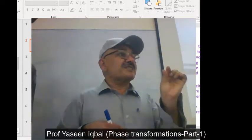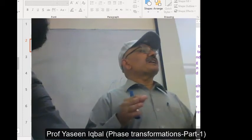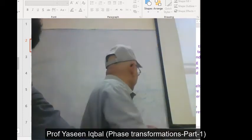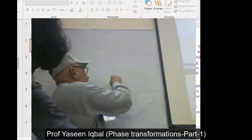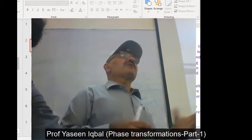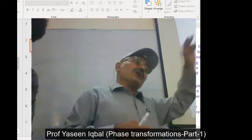Are you interested in crystallizing large crystals? Again, your DTA is telling you that. How? If you heat treat the material at the peak temperature, this peak temperature, heat it for 2 hours, you will see big crystals of that material throughout the volume of the glass.